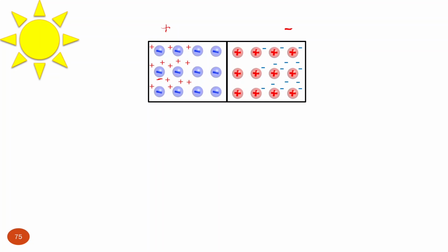So what is this? Any suggestions on what such a picture is? Do you have some association with what we considered before, when we have excessive negative charge and positive charge at the edges of the p-n junction? Capacitors, yeah, so it's related to that, though you kind of jumped over a few steps. The capacitance changes because of changing of the depletion region, and the depletion region changes because of applying external bias.